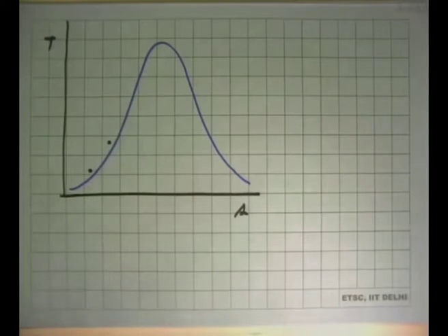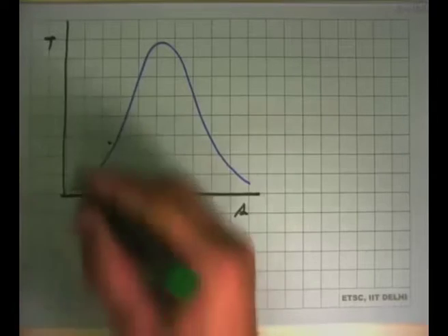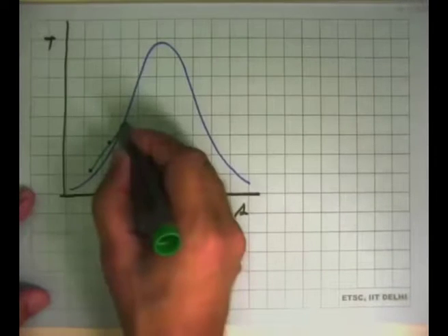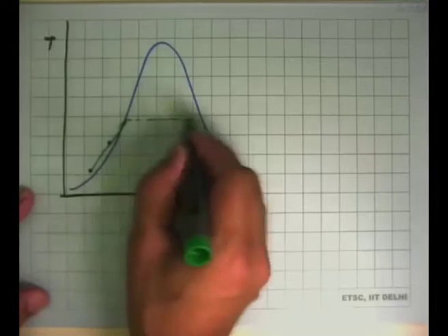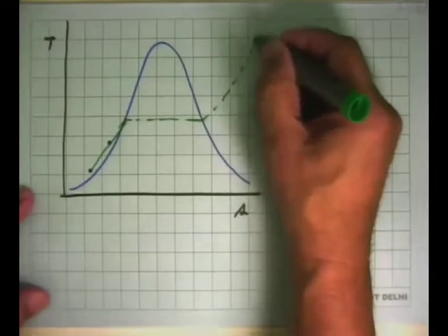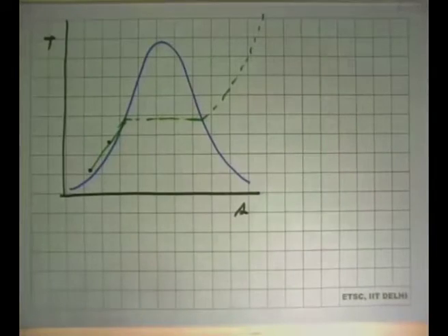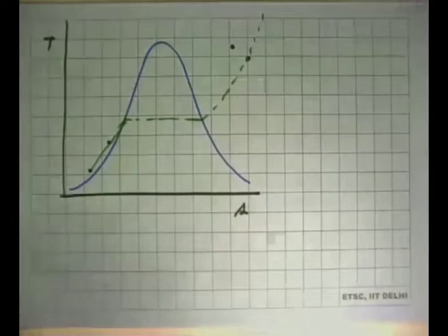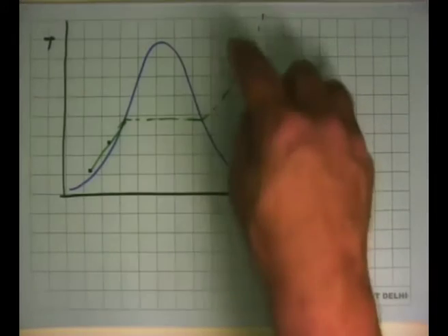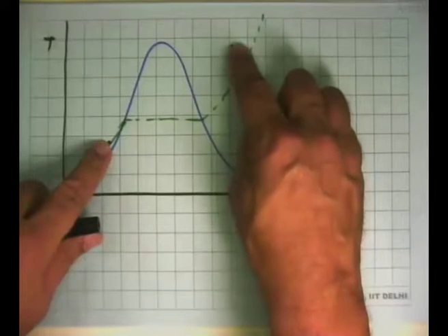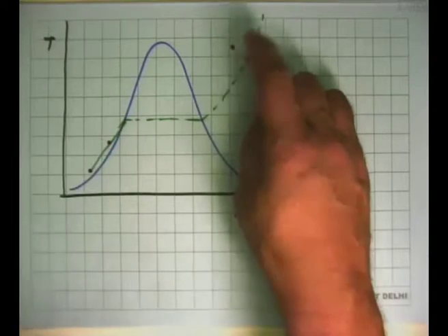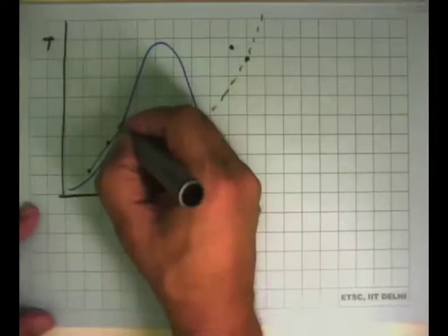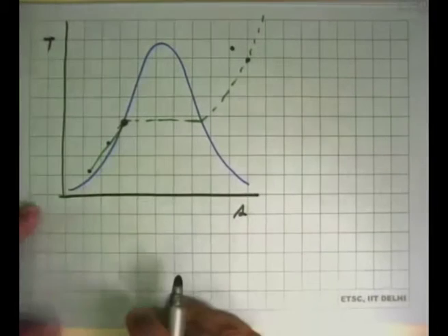If nothing would have been done, this is constant pressure heating, so this line will go off there, and then it will go there, and then this will go there. And we are mixing this with, say, superheated steam at the same pressure or at a higher pressure over there. So we brought this in contact with this, mixed it up, and we got saturated liquid at this state.